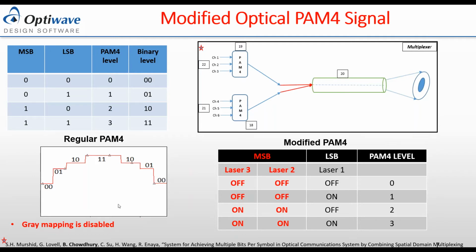So we could have two different laser sources to have that kind of output over there. We need to create multiple outputs over there. So what is the difference between LSB and MSB? You take one laser source and keep it for LSB, and you take two laser sources either in parallel or in series. We prefer to use them in series to save our power. If they are in series, then when the MSB signal comes to 1, both the laser diodes turn on at the same time.